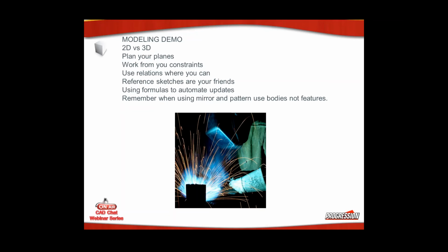The other thing is modeling with 2D sketches and tying things to geometry and assembling your model, your weldment, the same way it's going to be in the field, has some great power as far as being able to visualize what's going to go on. And we're going to look at all these shortly. But also planning your planes. If you want to model off of some planes and sketch on planes, again, thinking about the construction of it and how it's done.